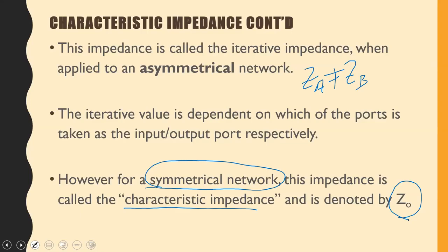If the network is symmetrical, and as I think it was Adams who asked, it means that the impedances at the upper terminals would be equal for the T network, and the ones that are vertical would be equal for the pi network. Because it is symmetrical, the impedance will be the same going from one direction as against the other, so the characteristic impedance would be the same. It wouldn't matter which port I'm looking at.